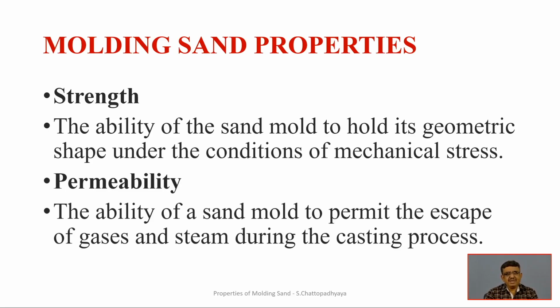The next one is also important, that is the ability of a sand mold to permit the escape of gases and steam during the casting process. The gases are trapped inside, and when they are liberated after casting, they will make a mark and jeopardize the surface finish and sometimes the quality of the casting inside.